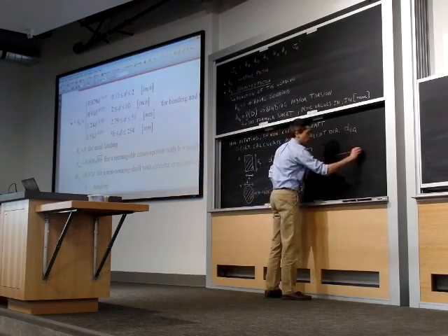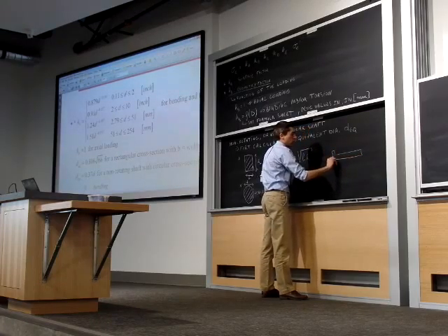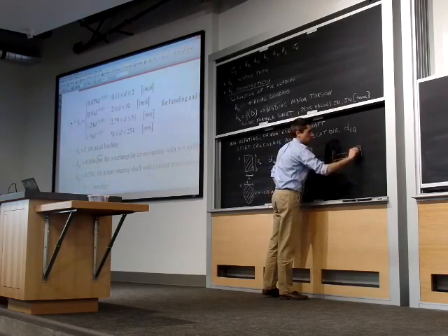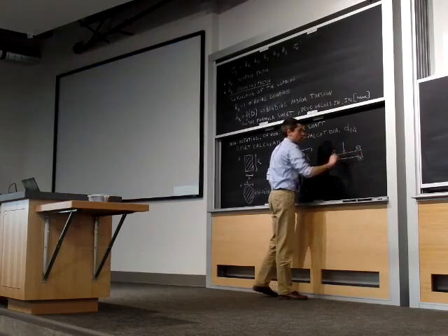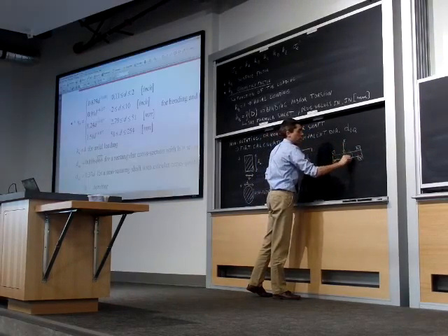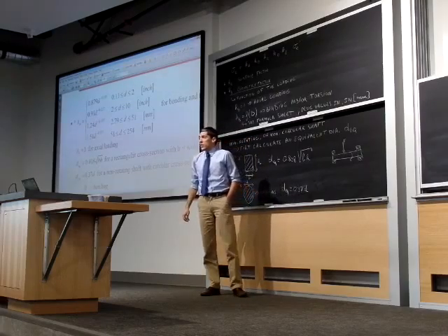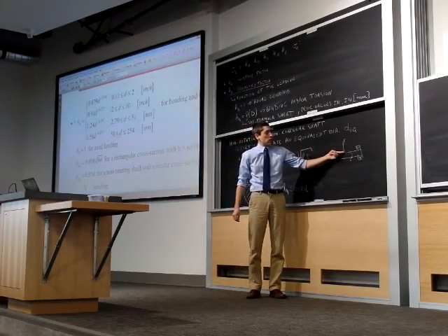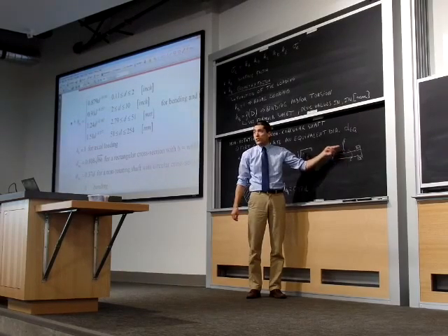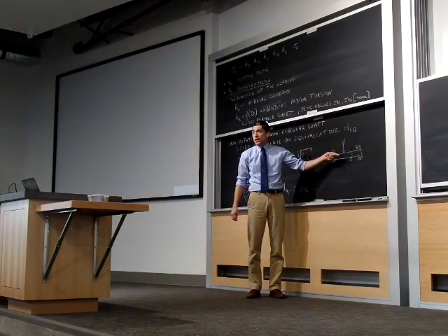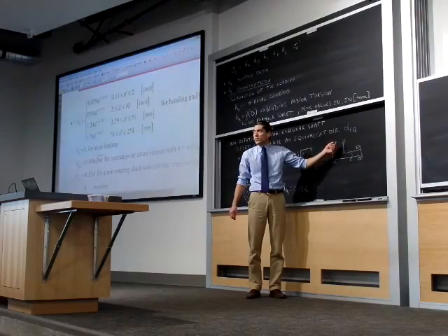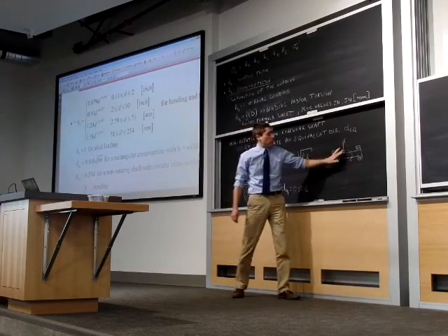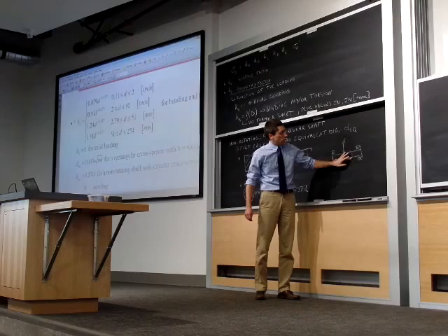Let me draw a shaft over here. Supported in two bearings, and I got a transverse load F, and first the shaft is rotating. Then you see that when your shaft rotates, you'll expose each fiber of the shaft to an alternating stress, and each fiber of that shaft is going to see the same alternating stress depending on how far it is from the neutral line, right? However, now let's assume that this is not rotating, but